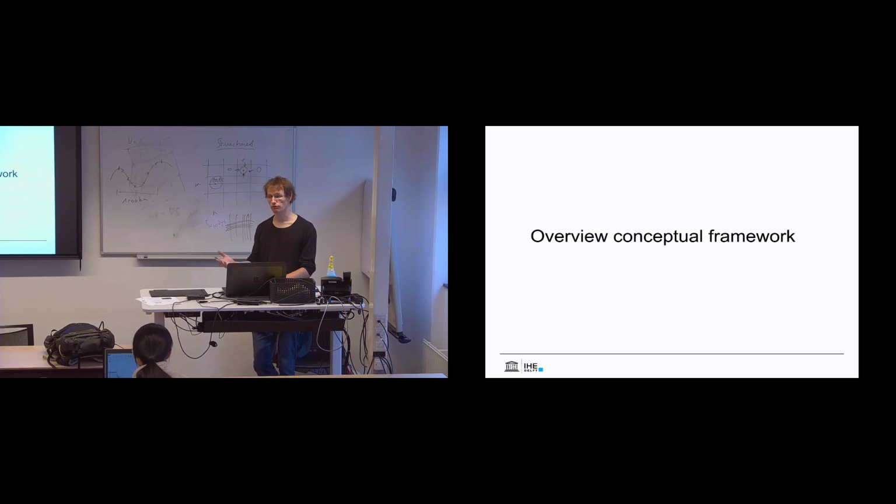For example, the wave model, D-Waves, is also shared. The hydrodynamic models they don't share. So the hydrodynamic kernels are separate. They don't share code. But waves is structured and communicates with files to flexible mesh, as it does with Delft3D 4. So it uses a different interpolator, but the concept is the same.